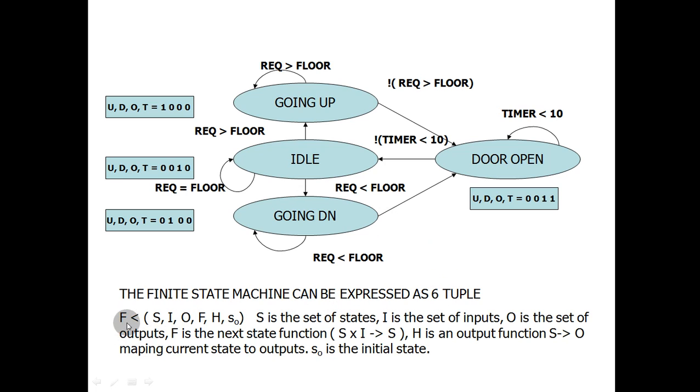This is F, less than S, I, O, F, H, S0. S is the set of states, I is the set of inputs, O is the set of outputs, F is the next state function, and H is an output function, mapping the current state to outputs. S0 is the initial state.